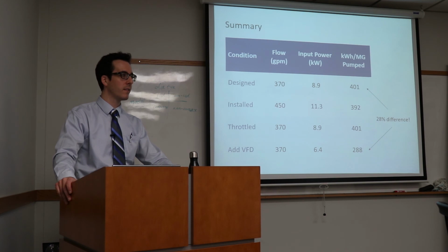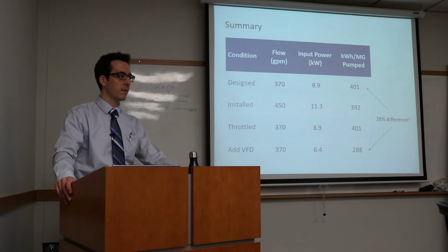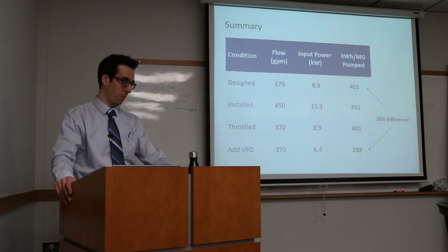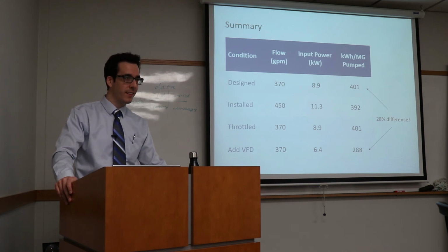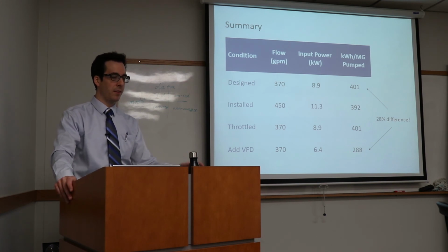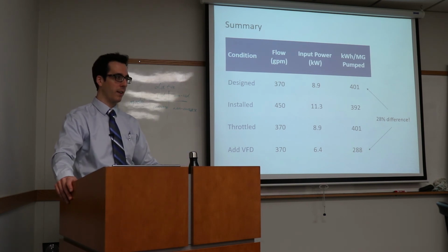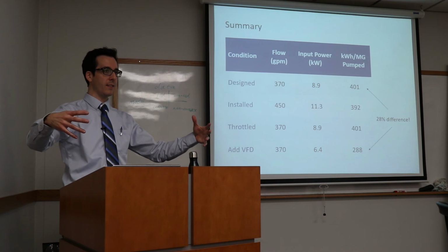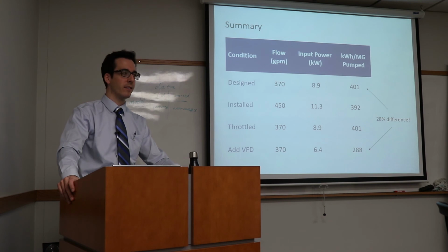How often do you see pumps in parallel or in series compared to one single pump that can just do the job by itself? In water systems, there's usually more than one pump, but that's just for redundancy. Especially in smaller water systems, they'll only run one pump at a time. The only time you'll see several pumps running together is something like a water treatment plant trying to match some kind of flow rate. Essentially, if you have enough pumps of different sizes, it's almost like having a VFD. You can respond to any demand condition.